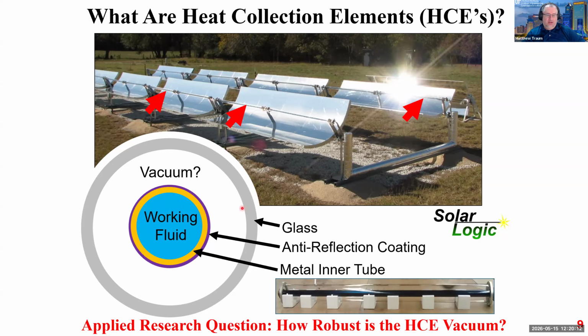And the purpose of the vacuum was, the sunlight enters through the transparent glass. It strikes this highly absorbing, very anti-reflective surface. It heats up the metal. The metal heats up the water. You guys have all, in theory, taken fluids, and so you could actually calculate, right, all of the flow associated with flow through a pipe, pressure loss, and what the velocity profile looks like in here. That also is important to heat transfer.